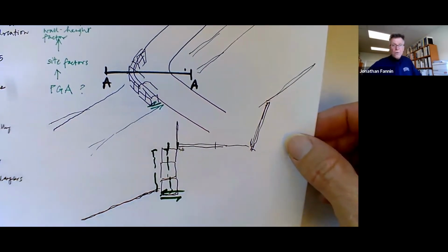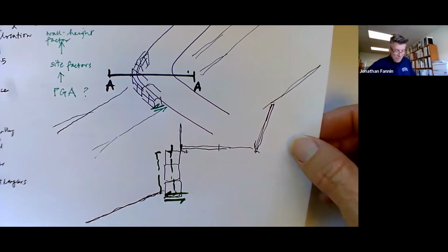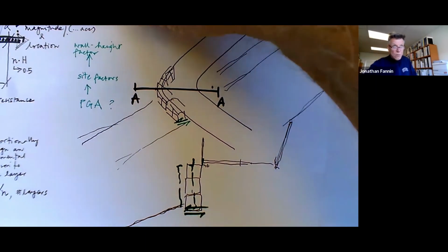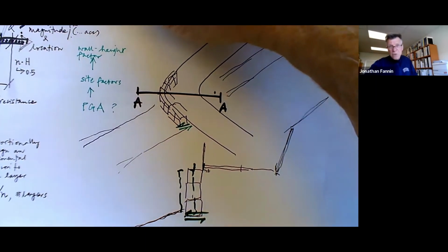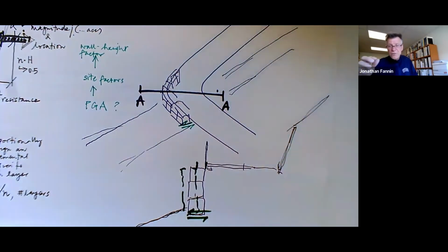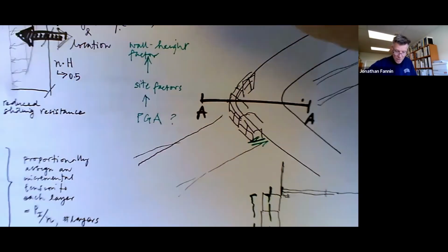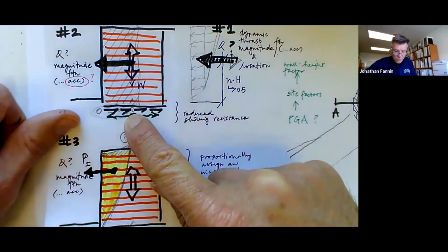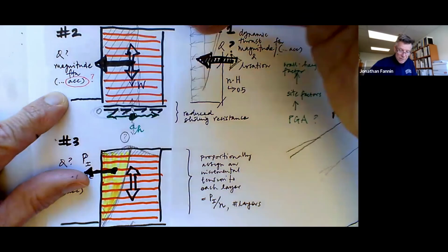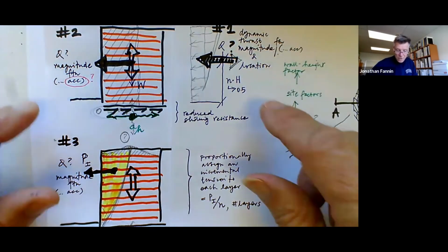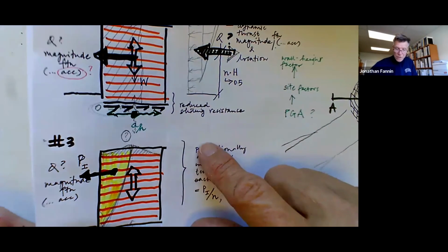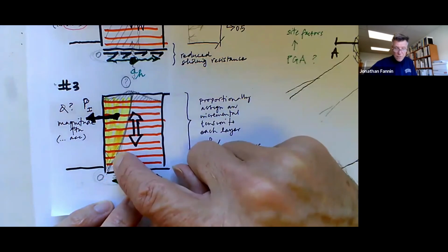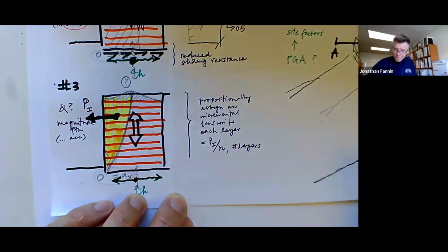So no concern that I saw in any of the structures I visited that were geosynthetic reinforced, of which there were 3 or 4 in a total number of wall visits of about 10 or so, because of so many different systems that are used. But the issue was one of sliding, where the ground was falling away and the loadings from the slope were probably quite aggressive. But no concerns that I observed for aspects of tensile failure at all.